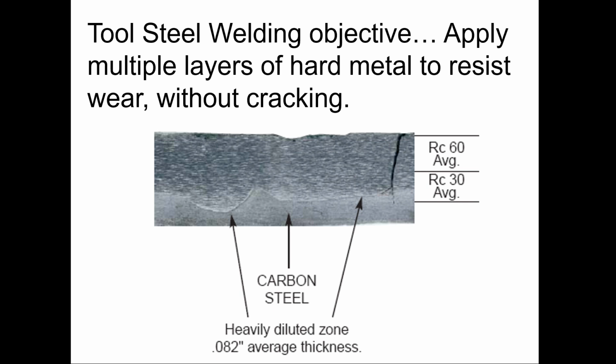But if you put another layer on it, if we get up here and put another layer on it, the Rockwell hardness gets quite a bit more. Point being, the more layers of hard material you put on, the more of an effect you're going to have on the hardness, to the point where you might get a little bit of a crack. So you've got to be careful how many layers.